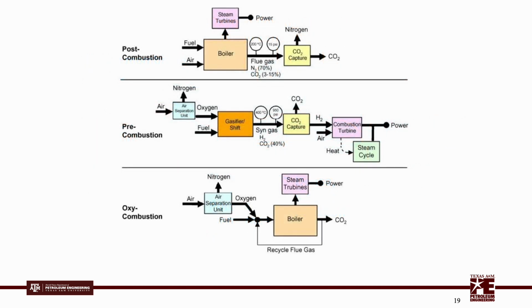Previously, we introduced three methods of carbon capture. Post-combustion capture is useful for separating CO2 from exhaust gases created by burning fossil fuels. Pre-combustion capture refers to removing CO2 from fossil fuels before combustion is completed. Oxy-fuel combustion is a fairly new approach to power generation.